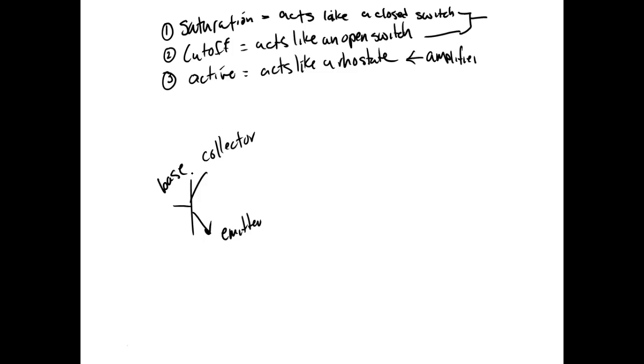So we've got this voltage called VCE, voltage collector to emitter. If we measure VCE, we can determine just like that what region it's operating in. So I take my meter and put it on volts, and I measure right there. That would be my voltage collector to emitter. This is what's common, so the one on the right is where you put your black lead. On transistors, you really need to do that, because to bias the transistor, we have to have certain polarities, right? You understand that? Okay.